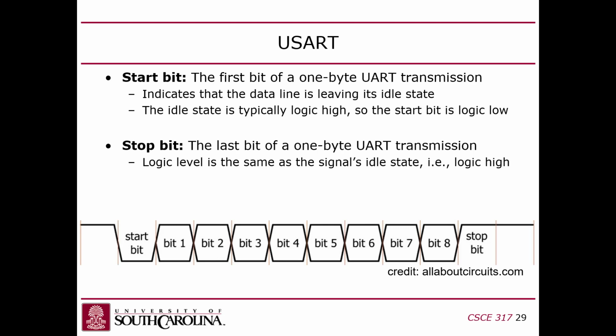So basically, the format is a sequence of bytes, generally 8-bit bytes, and you serialize them. You have an 8-bit byte and you want to send it across a 1-bit wire, so you just send 1 bit at a time. And it goes from least significant to most significant. So you're essentially reading the bits of a byte from right to left.